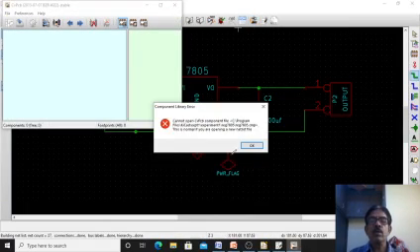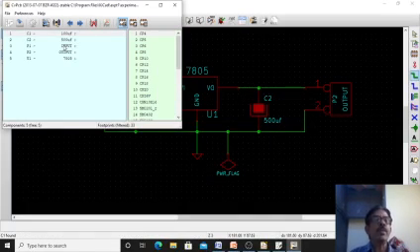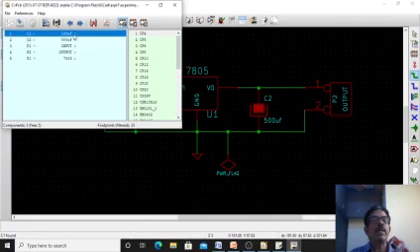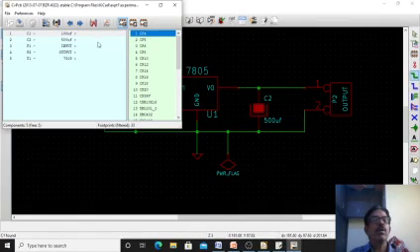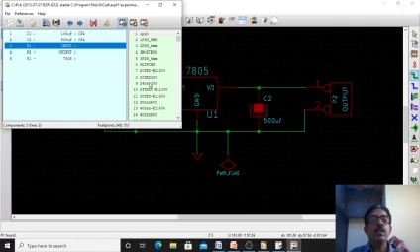So you just click on this. You have to associate footprints for each one. For C1 you take it, here click on this, double click on this, then for example I will take CP4. Double click on CP4. It is a standard size. CP4, CP5, anything you can select. So I have taken CP4, and for C2 also you select CP4, and for port 1, that is for this, you select SIL2, serial inline is its full form. You just drag it, you will get SIL2 here.